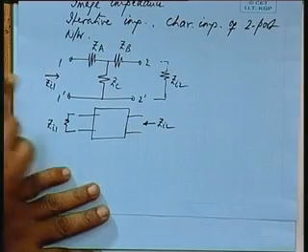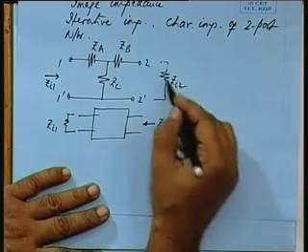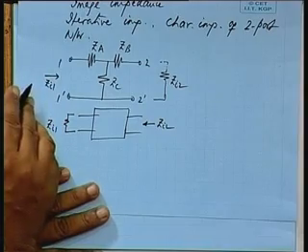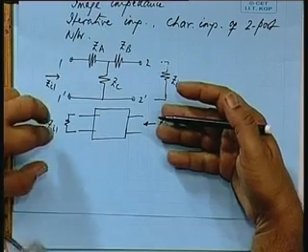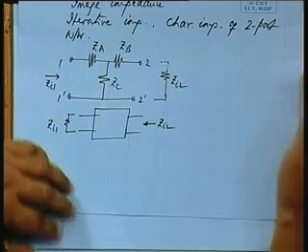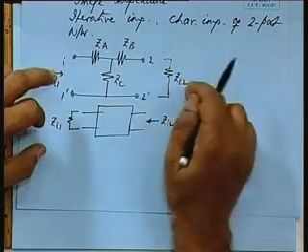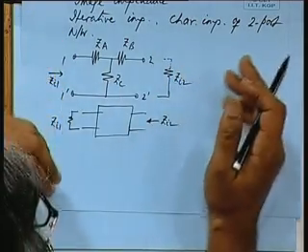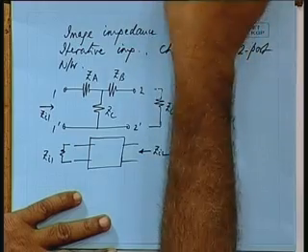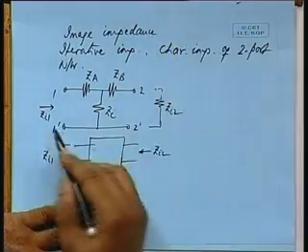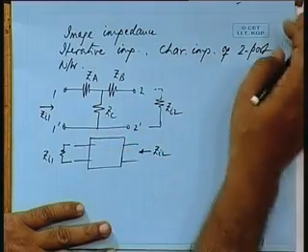You look into the circuit from this end, if I load on that side ZI2, then the impedance in is ZI1. If I look at the network from this end and if I load it with ZI1, the impedance in is ZI2. Mind you, you cannot have these unique values with any set, you cannot have any combination. So, these values are dependent on ZA, ZB and ZC. Let us see what will be the relation between ZI1, ZI2 and these element values ZA, ZB and ZC.